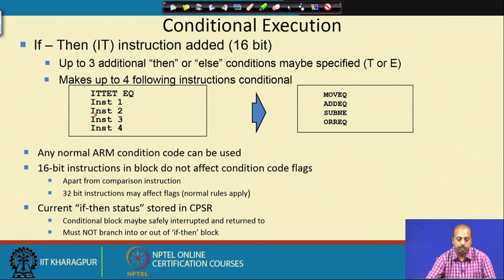So, you cannot take a branch instruction from here before completing this if then else. You cannot have the third instruction as a branch out instruction, or you cannot just branch into a block. You cannot say that I will jump onto the middle of this block. That is also not possible. So, this M3 processor has got many interesting features, and many more features are there.